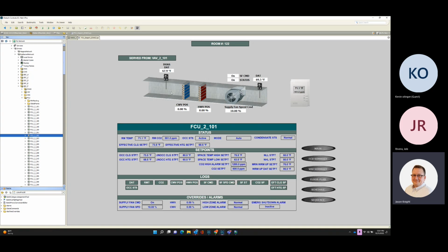So we're very carefully monitoring what the demands are for the room. And then when the fan coil changes speed, it signals the demand control ventilation in the variable air volume box to update its flow set point. So the VAV box is always following the fan coil. Does that make sense? Because we don't want the VAV to overpressurize the fan coil.